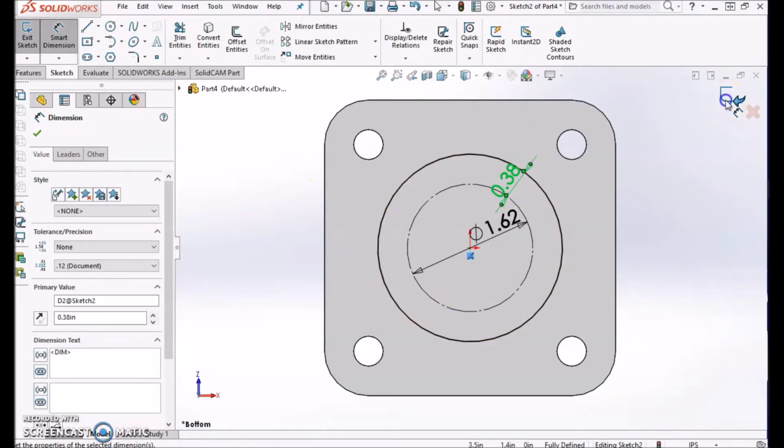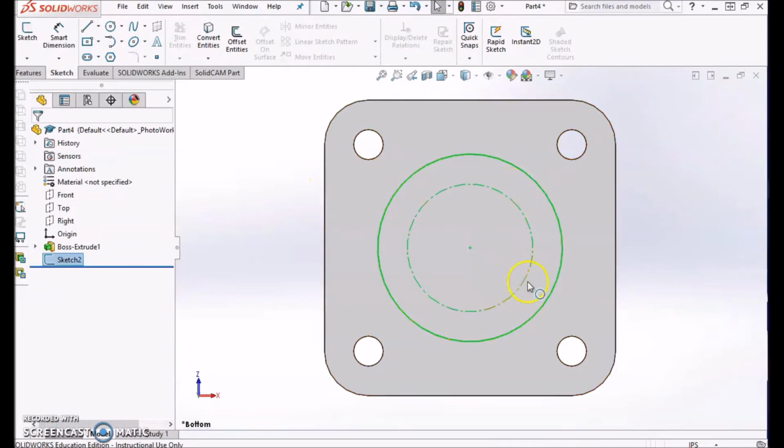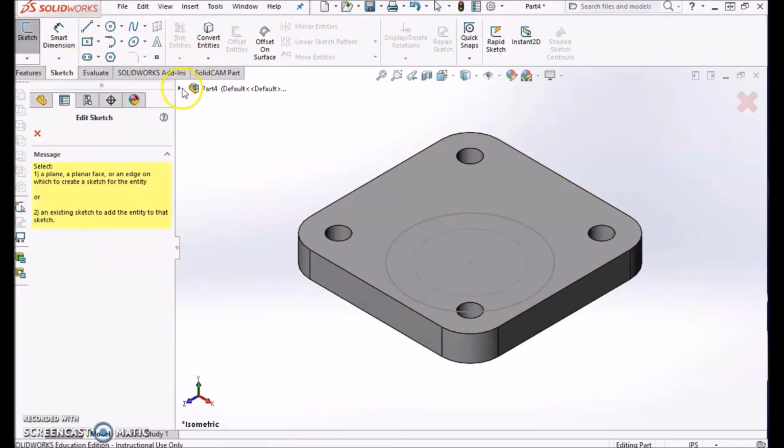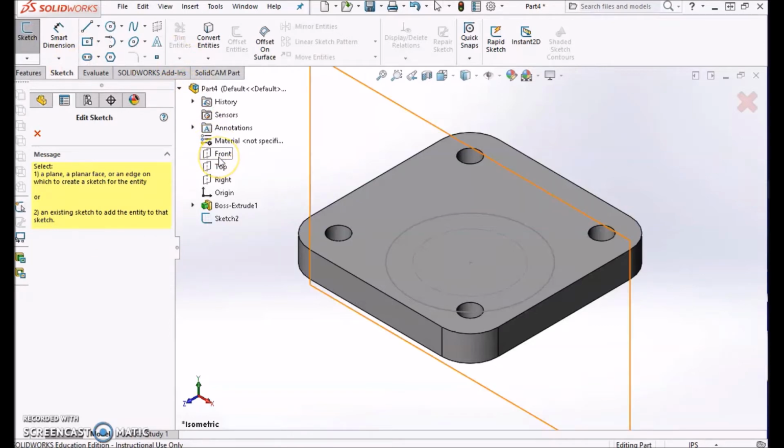Okay, I'm going to hit Return from Sketch in the top right to get out of that. I'll hit Control 7 to go back to a good view, to an isometric. And here we need to draw that arcing piece. So I'm going to hit the Sketch tool, and we need a plane. So if I hit that drop down, we can kind of look at the planes.